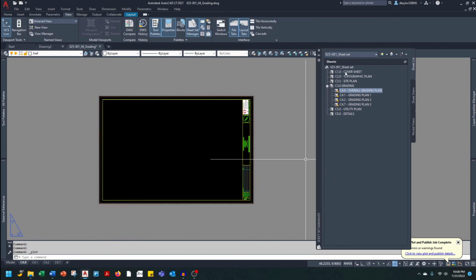When you do go and publish the entire plan set, the print setup will be ready for you. You know, if someone goes in and just prints off like a little 8.5 by 11 area right here, they need to get in the habit of going back into the page setup and setting it to the 24 by 36. All things considered, I think it's a small cost to pay for the immense benefit you get from publishing this plan set using the sheet set manager.